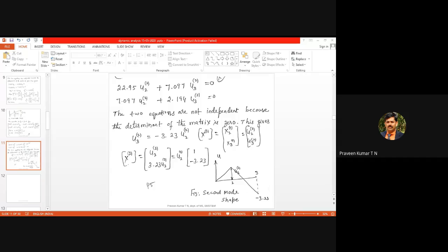When t is equal to 0, you are starting. Then you are exciting the structure, you are putting energy into the structure. Once you put the energy into the structure, the energy is absorbed by the material. That is nothing but kinetic energy. It will be stored in the form of elastic energy or deformation energy. Even though you are removing the excitation, even if you stop the engine itself, the system will still vibrate.